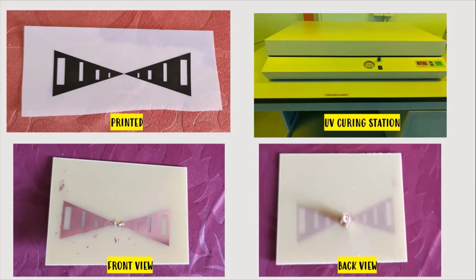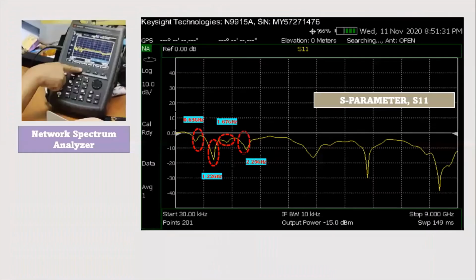So as we can see, the middle wire is actually the soldering for the SMA 5-pin female connector, because by using this female connector, we will connect to measure the signal, S parameter, and VSWR. So to measure the VSWR and S parameter, we use the network spectrum analyzer.